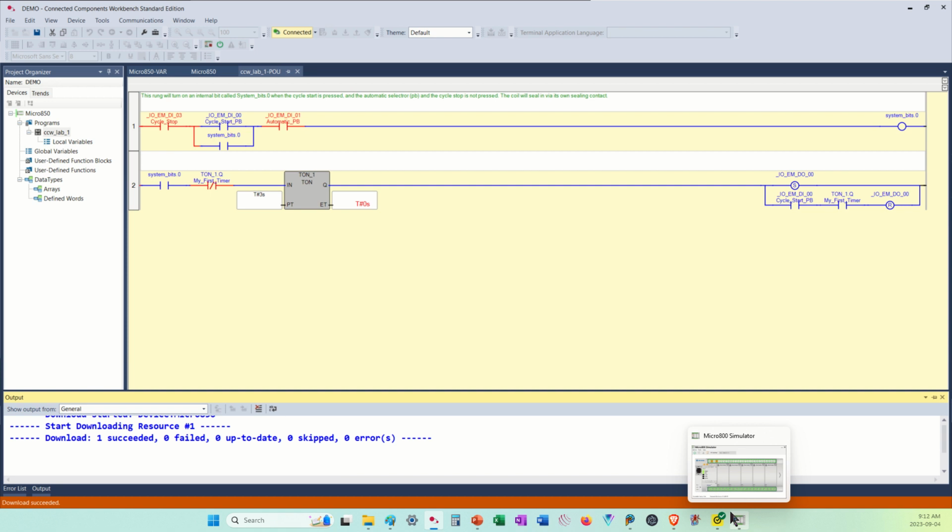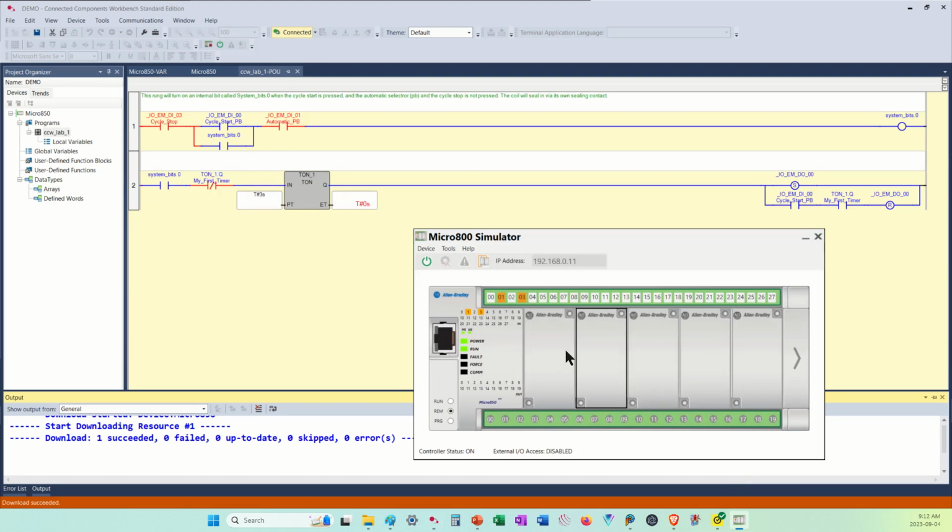So I'm going to call up my simulator again. I'm going to double click that really fast. And let's see what happens if I corrected my problem after 3 seconds. Oh, my set is on. So my output's on, but it's not turning off. Huh. Oh, I made the same mistake, I had my push button again. I had to push my push button to reset that.